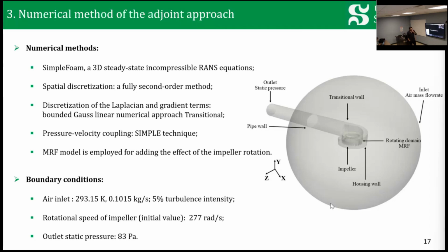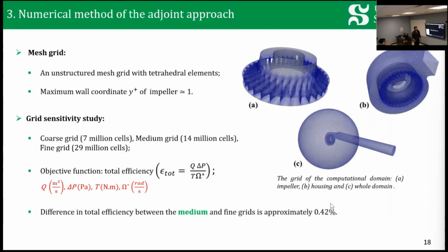Since we simulate in steady form, the MRF model is employed to add the effect of impeller rotation. A mass flow rate of 0.1 is imposed at the inlet, and the initial value for rotational speed is set to 277 radians per second, and a static pressure of 83 Pascal is imposed at the outlet.